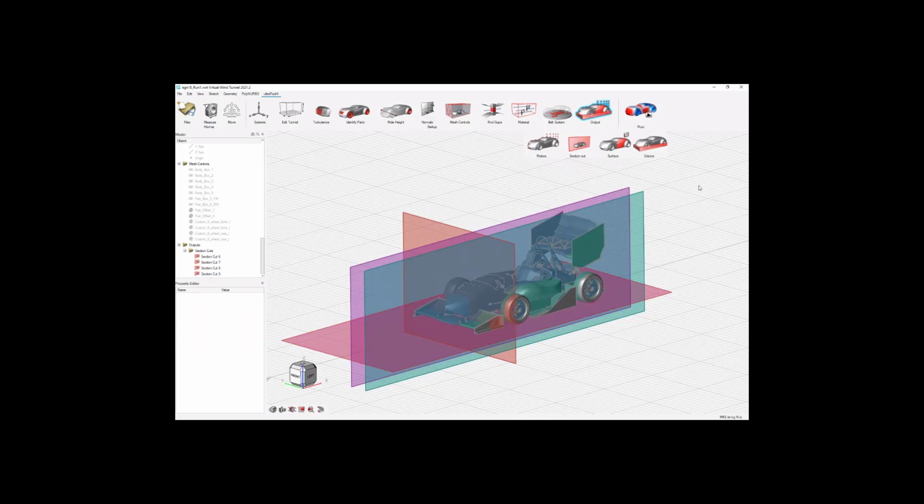So let's export the simulation. For that, just click on the triangle icon at the run icon. Now here we can choose the name of the run and the number of GPUs we will use. In my case this will be 8. Here we could also change the inflow speed again, but we already did that.